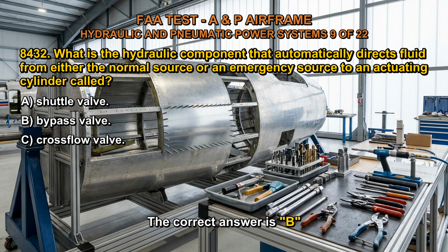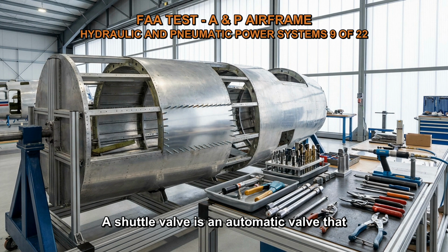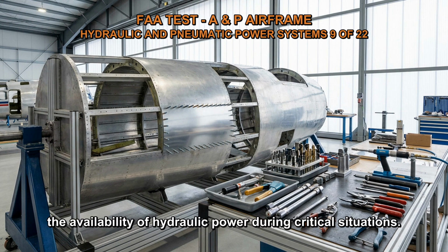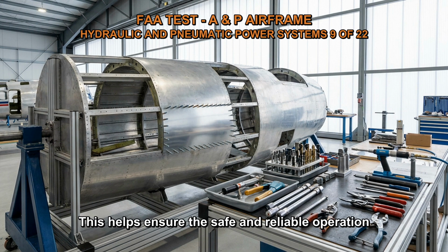The correct answer is B. A shuttle valve is an automatic valve that is typically installed on a landing gear actuating cylinder or brake cylinder. Its purpose is to direct the normal system fluid into the component for regular operation. However, in the event of an emergency, the shuttle valve automatically shifts to allow fluid from the emergency system to enter the component, ensuring the availability of hydraulic power during critical situations. This helps ensure the safe and reliable operation of the landing gear or brake system in emergency scenarios.